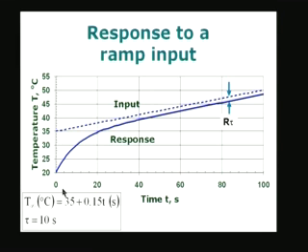In this slide, I have taken T infinity, in degrees Celsius, given by 35 plus 0.15 T, where T is in seconds. The time constant of the sensor I have taken as equal to 10 seconds, and I have shown the plot when the temperature of the sensor was 20 degrees to start with. Initially you see the temperature is increasing and trying to catch up with the temperature of the ambient, which itself is again increasing, and therefore it will never catch up completely.